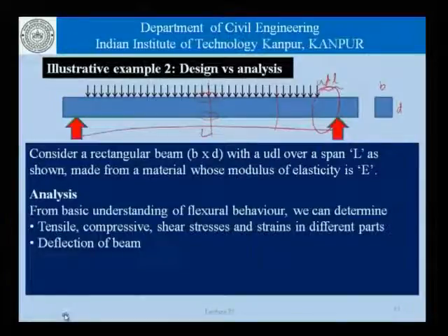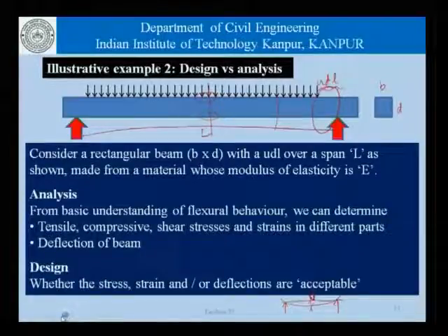We know that a beam which is subjected to certain loads deforms, and this deflection is something which we can calculate from our understanding of flexural behavior of beams. Now, what is the design? The design exercise really means whether the stresses, strains and/or deflections are acceptable.